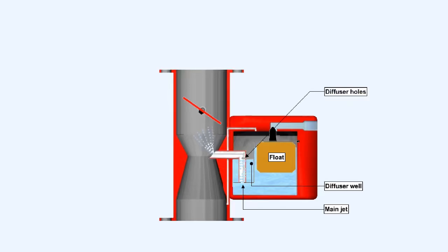A number of small holes are drilled through the wall of the fuel discharge tube at different levels. As engine speed is progressively increased above idling, the fuel level in the diffuser well drops, and progressively uncovers more air holes which allow more air into the discharge tube, and by reducing the pressure differential prevents enrichment of the air-fuel mixture. The process of drawing both air and fuel through the discharge tube also has the effect of vaporizing the fuel more readily, particularly at low engine speeds.